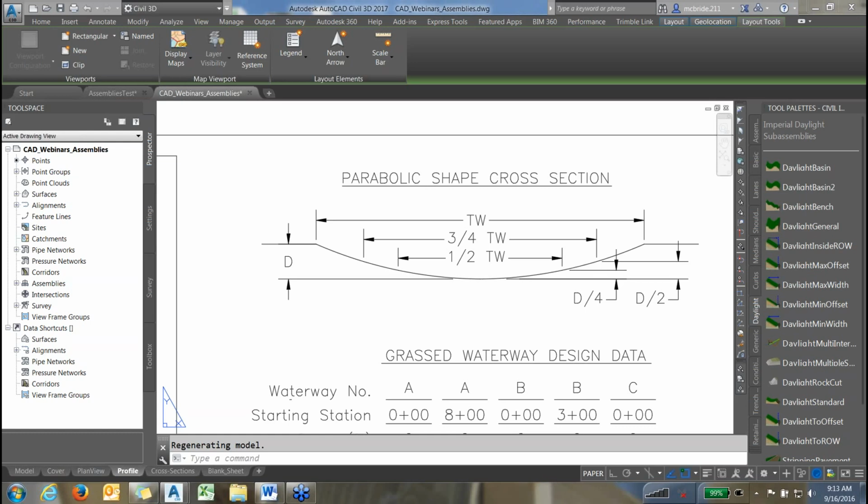You can do this same process to do a small dike, levee, or dam. Same thing, just flip it upside down. Instead of drawing a ditch bottom, you'd be drawing a dike or dam crest with side slopes, daylighting to a bottom. You could do it for a core trench, a two-stage ditch, just drawing in the flat benches, a three-stage ditch, or any type of shape like that could work real easily. You just have to pre-calculate your lengths and slopes.